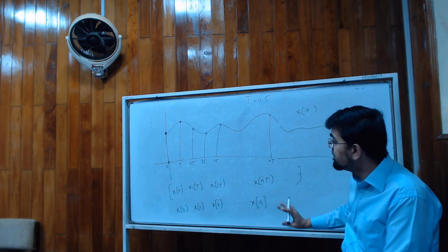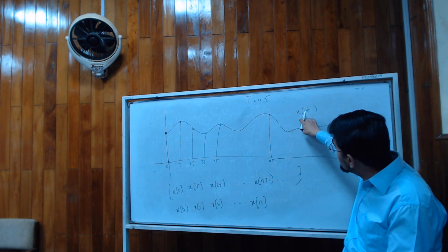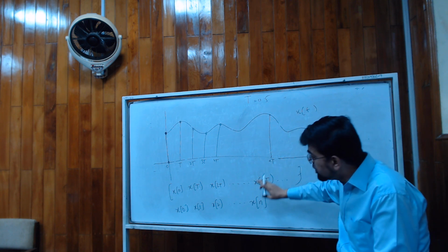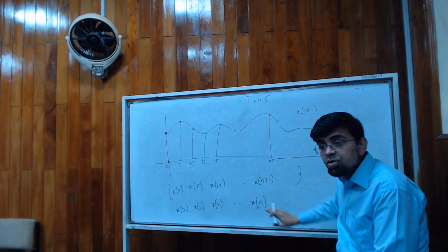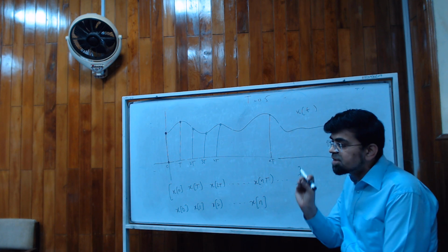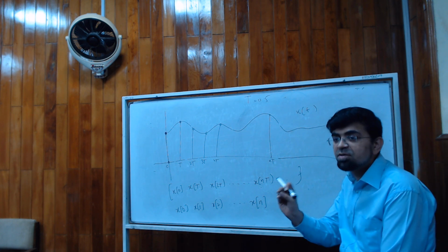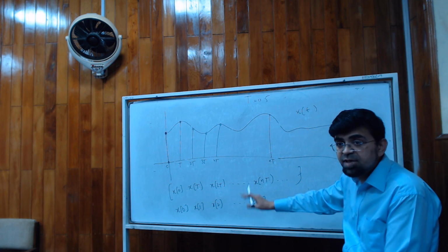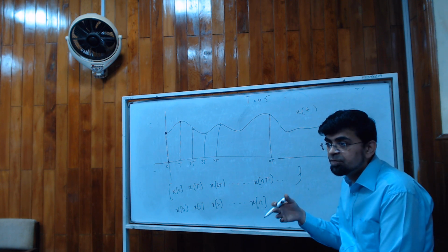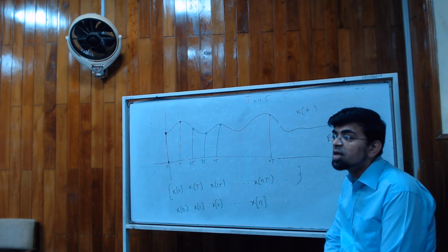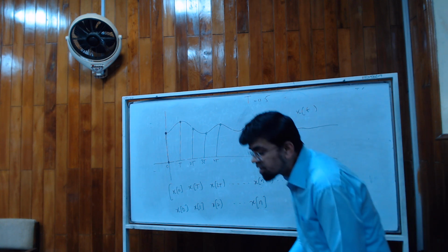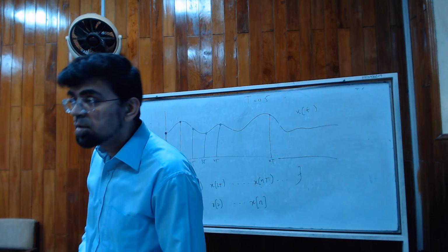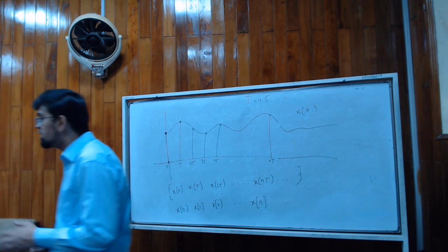Now the thing to remember is that in reality the continuous time signal is this, the samples are here, and we usually write it like this. So whenever somebody gives you a set of discrete samples, or says this is a discrete signal, and they say the 0th value is this, the first value is this, what should you ask for? First thing, sampling time. So this is very critical. A discrete time signal is incomplete without the definition of its sampling time.